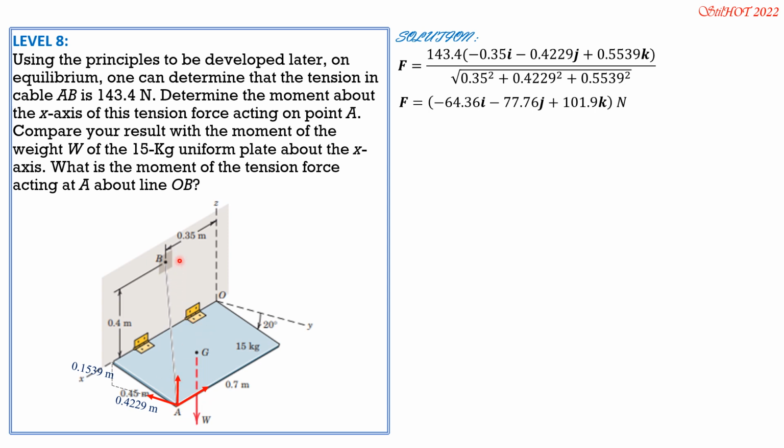Now this is the tension force, and this is the x-axis. If this is your right thumb, the positive sense by scalar approach is in that sense. Therefore, Fx, parallel to the x-axis, has no moment. This z component will have the same sense, positive sense, so its moment is positive, while this y component is negative. It comes from below, then it curls that way. The positive moment is, the curling is in that sense. So this is Fz,